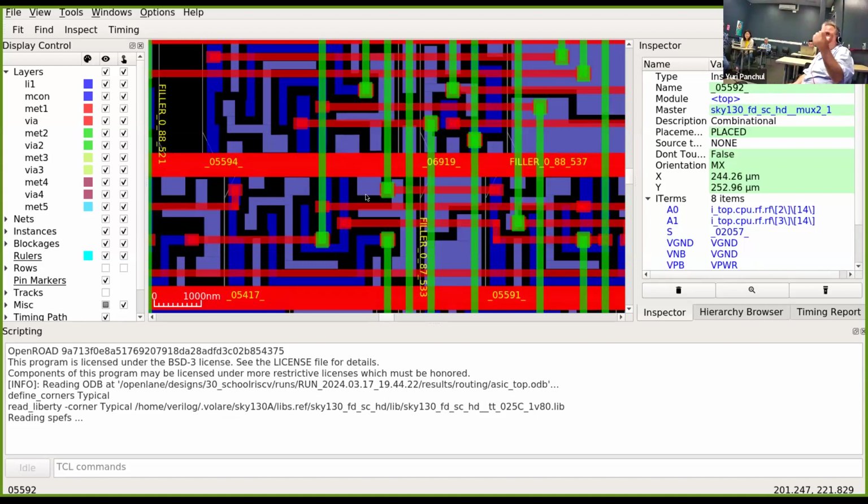So when a design goes to the foundry, it gets a file which has polygons, rectangles, saying that this is the area of silicon with a little bit of phosphorus, and this is silicon with a little bit of boron, and here is a metal wire of copper. In old times metal wires were aluminum, and then they switched to copper wires, and there are many such layers, and this is all defined in a file with the GDS2 format, and this is a viewer of such a file.